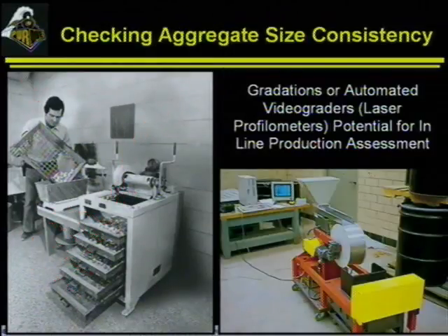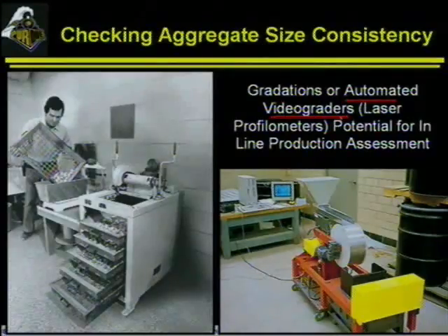I will mention that there is quite a bit of interest in moving to something that gives a little bit better information, and you're seeing people now move away from sieves, or at least talking about moving away from sieves, to automated video graders, lasers. There's actually a group at NIST who does X-ray on aggregates and then models them like they're little asteroids to get surface characteristics. It takes them about a day to do each rock. It's not a commercial application yet, but I think some of these things you're going to see very commercial very soon.